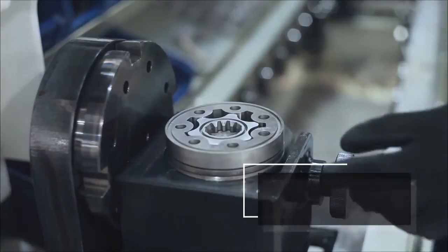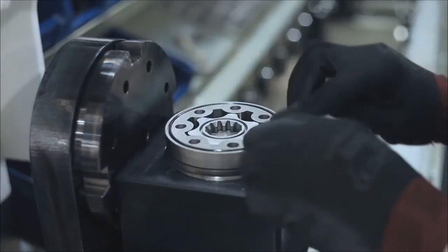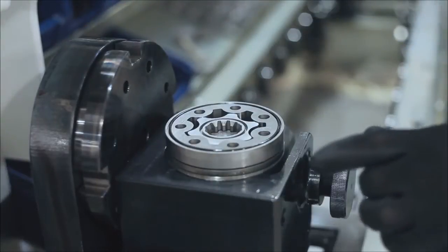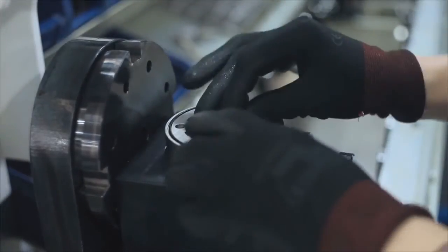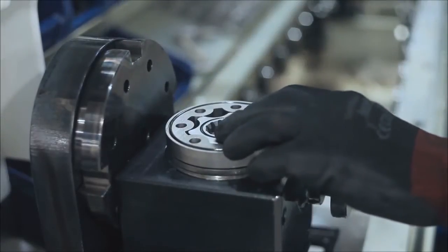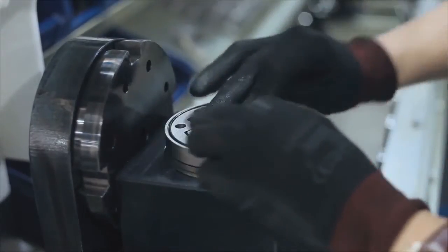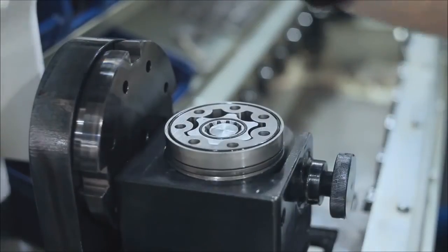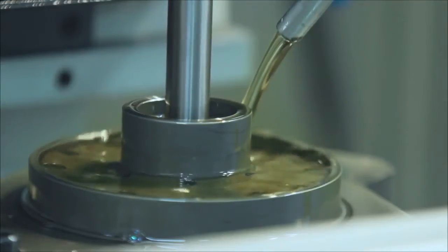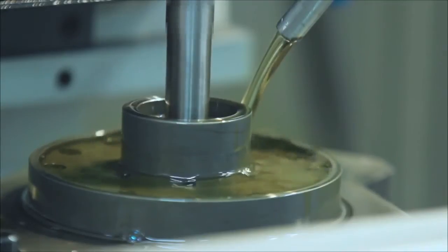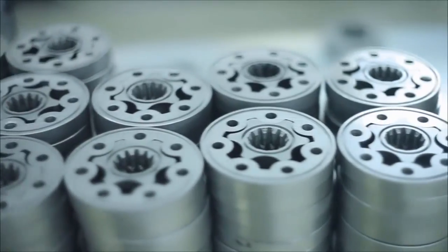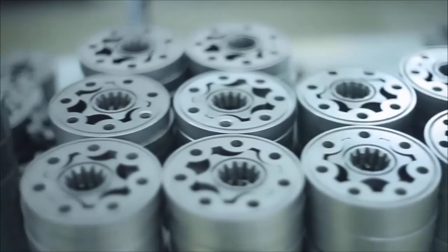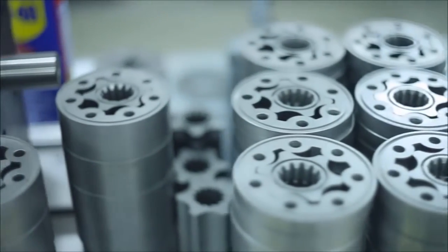Another key aspect of GD&T is to make sure that the features on a part are dimensioned to reflect how the part is actually used in its final installation. The designer should not give consideration as to how the part will be manufactured, whether it is forged, stamped, machined, or molded. Each of these processes will have varying capabilities that will result in different types of variation.